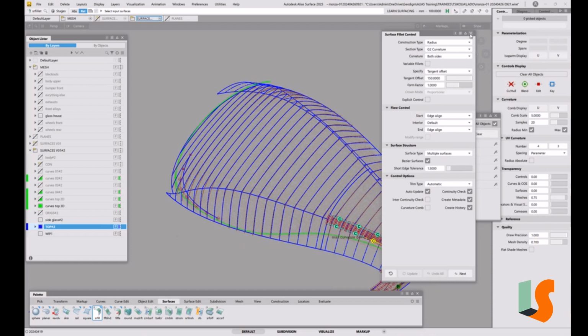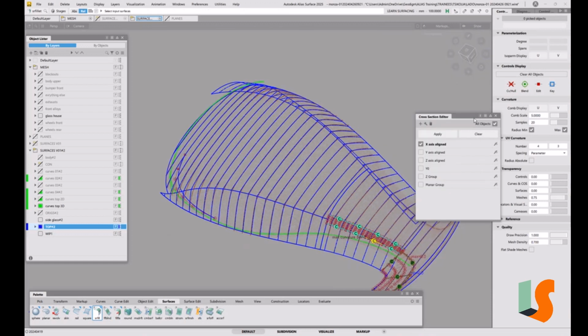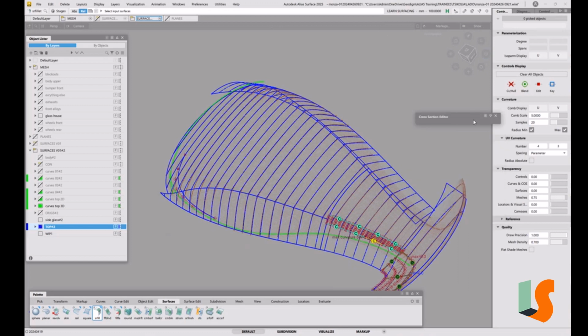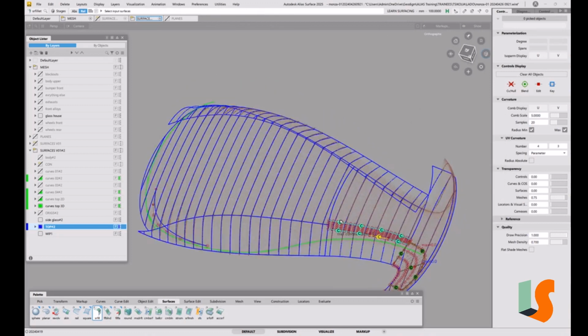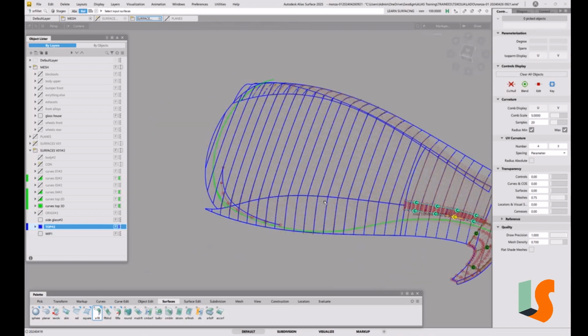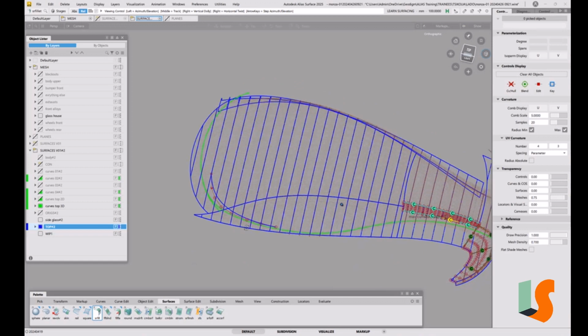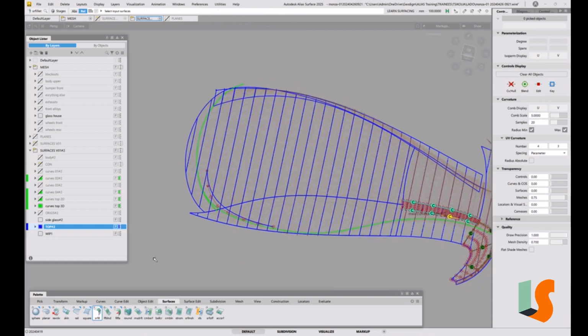It's just too dramatic. I think this is going to be difficult anyway to get a nice transition between the two. We might have to open this up as well. But in this situation, we often want to do a manual type fillet. So one option is we've got this thing called symmetric fillet. I don't know why it's called symmetric fillet, because it's not symmetric, but it takes one edge. So if we put in a curve, say from here to here, curve on surface, then we can actually fillet between that and the other surface.